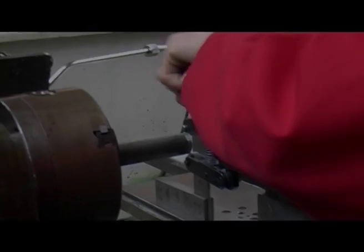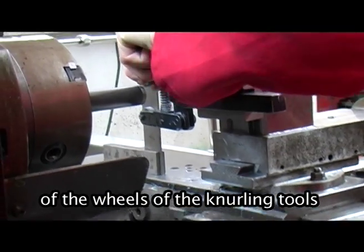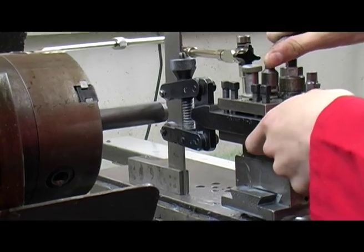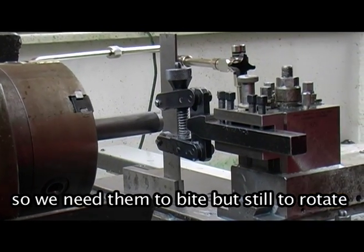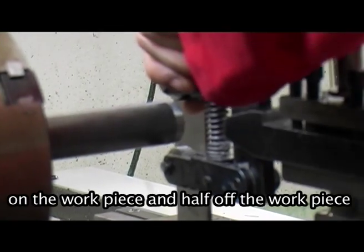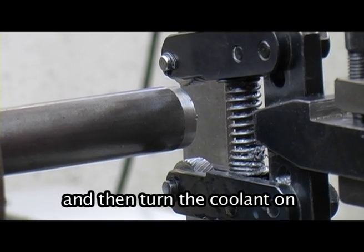Step 4, we now hand adjust the tightness of the wheels of the knurling tool onto the workpiece. So we need them to bite but still to rotate, with half the knurling tool on the workpiece and half off the workpiece, and then turn the coolant on.